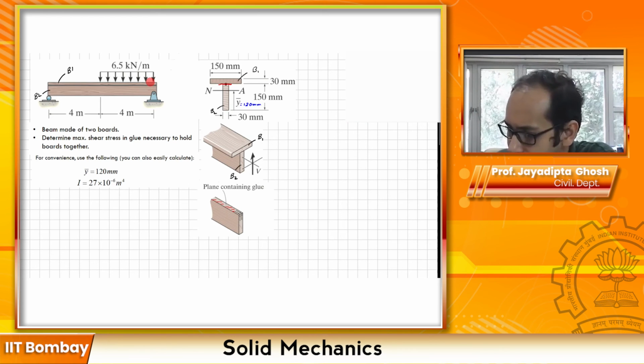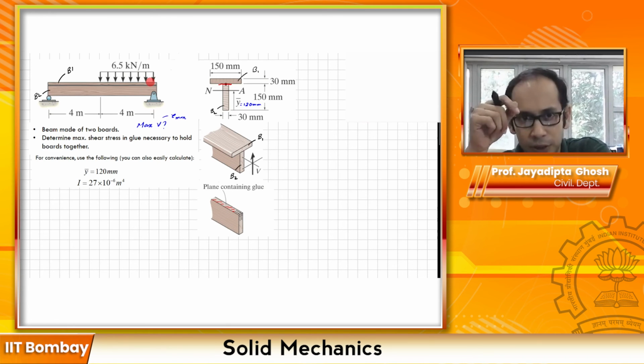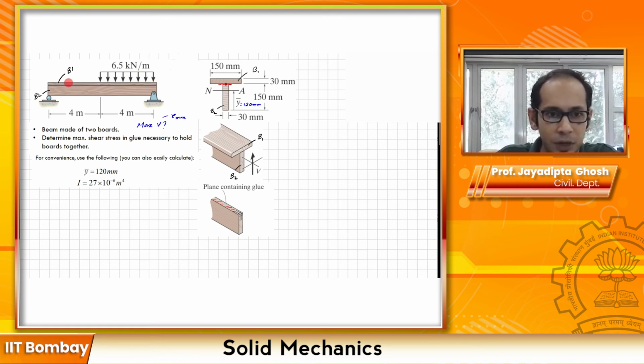So we are trying to find where in this beam this max V occurs, and this is the place where your tau max will also happen at that glue, because the maximum V will give rise to maximum transverse shear and complementarity, and from complementarity you will have the maximum longitudinal shear, which is resisted by the glue, because longitudinal axis means along this axis over here.